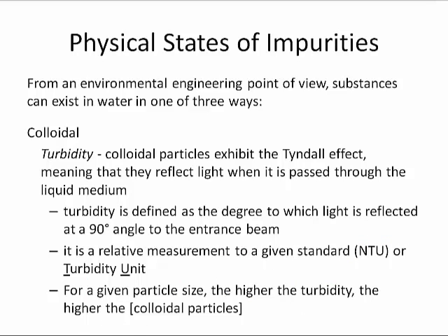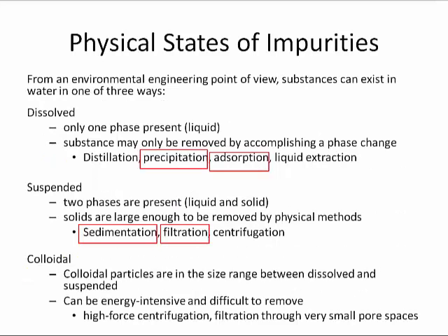Colloidal substances are often measured as turbidity, and so we will often refer to the turbidity of a water. Turbidity is simply a laboratory technique whereby light is shined through a solution and the reflection of this light is measured. It is given units of nephelometric turbidity unit, NTU, and so the higher the NTU, the higher the turbidity.